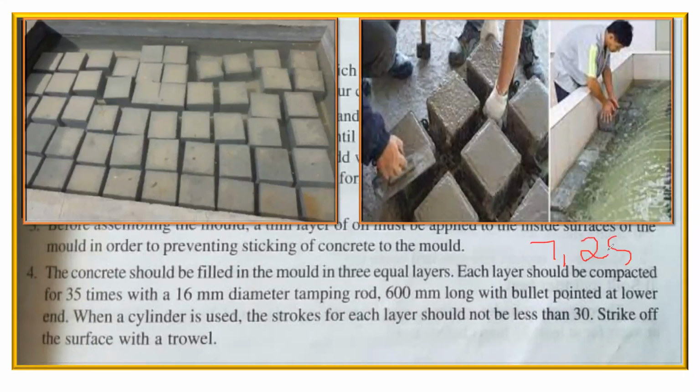In some labs we also do it on 3 days. But the general practice we follow is the 7 days and the 28 days. The final strength we take for our calculation is the 28 days, because based on the 28 days strength only we'll decide what grade we want, right? So this is how the entire process of a cube testing has to be done.